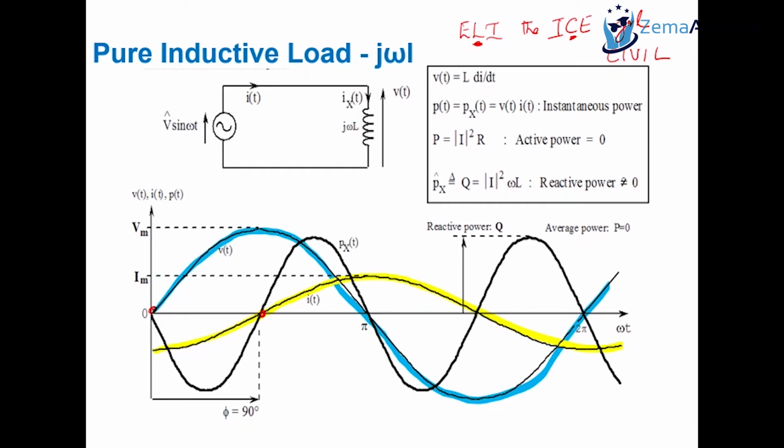Usually in consumer distribution, voltage is taken as a reference because the expectation is that when you supply power to a residence or a building, you supply power such that the voltage available stays at 230 volts, no matter what happens. Therefore, that is our reference. And everything else, all the currents within the various loads drawn in that building are given as a reference to that voltage. Okay, so always, for most purposes, voltage is a reference, and the voltage at the load end is usually taken as the reference, not the voltage at the generator.